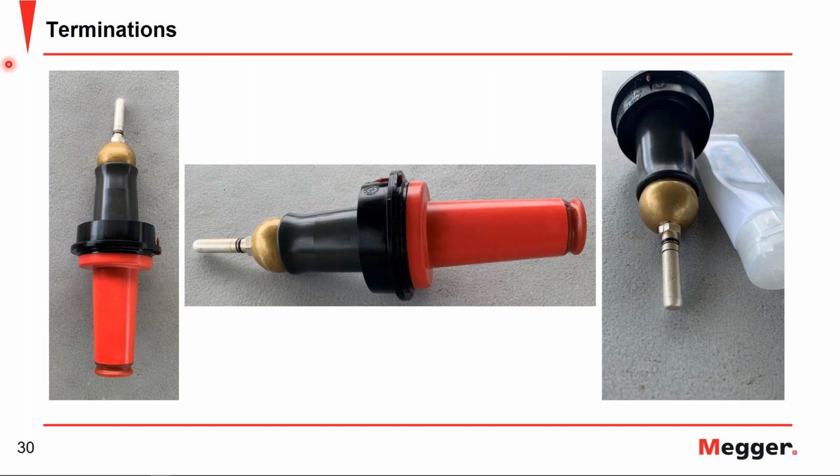Next is how to connect into your load break elbow, or how you're going to connect your high voltage cable to that load break elbow to test that cable. And this is kind of that custom solution that we had talked about, where we took this bushing well insert, where we would insert here into the elbow, and then this is going to be our test point, where we have a corona ball and an MC connector that allows us to just simply connect the high voltage cable on.